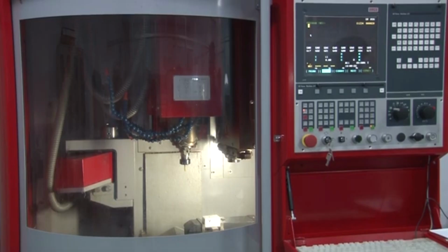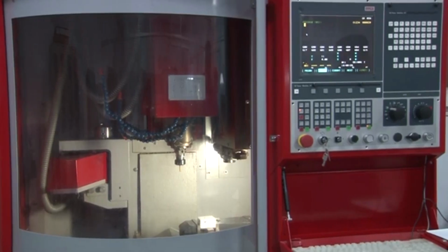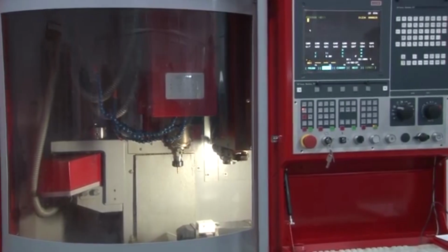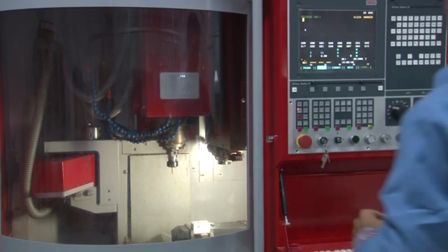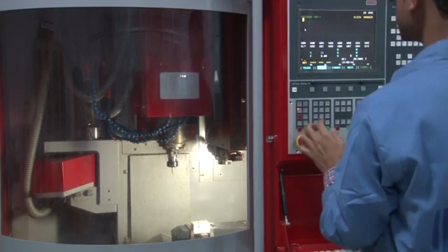Now, the tool you can see there, that is mounted, is the required tool for the current fabrication, and the command will be given to bring the tool from the reference point to the 0 point of the workpiece. Okay. So, you give the coordinates and it will be in the jog mode.